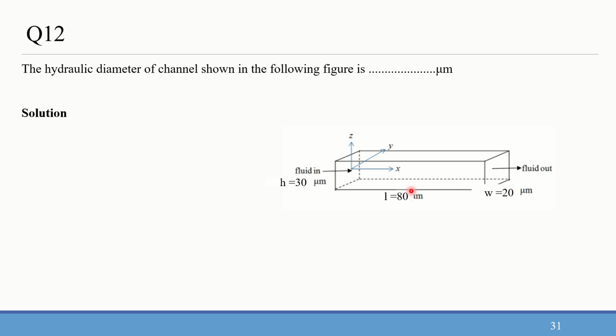When we calculate this hydraulic diameter, we can apply circular flow principles to non-circular ducts and channels. This diameter we can use to calculate the Reynolds number.